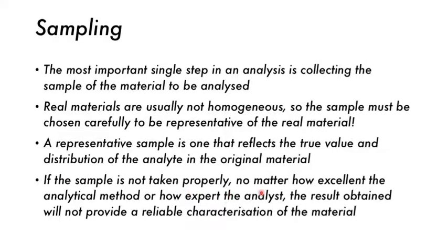So if the sample is not taken properly, no matter how excellent the analytical method or how expert the analyst, the result obtained will not provide a reliable characterization of the material. It doesn't matter how fancy or expensive your instrument is, if you don't choose the sample that you measure properly, the results that you get out of the end are going to be meaningless.